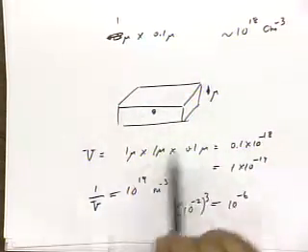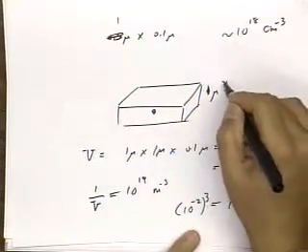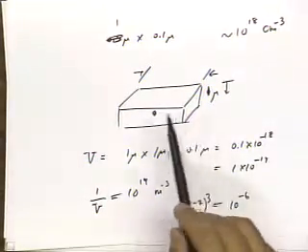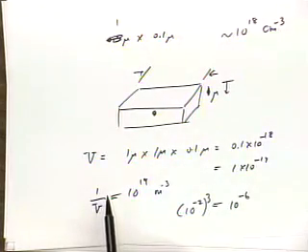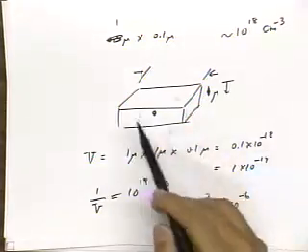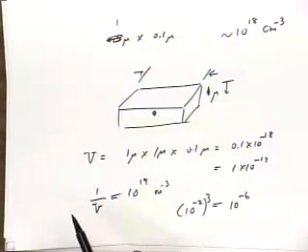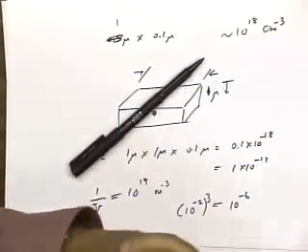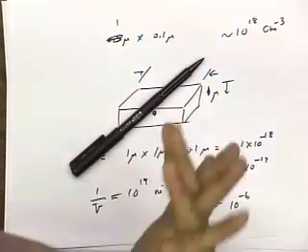As you shrink this volume down more and more, you get into the situation where instead of having 1 million dopant atoms, you end up having just hundreds of dopant atoms. And then when you fluctuate just a few atoms, you find the threshold voltage fluctuates considerably. So if you're dealing with new technologies, let's say below 45 nanometers, then fluctuation of dopant atoms is a huge effect. So that's one issue.